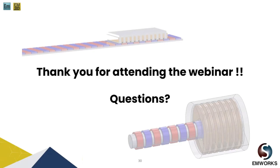of course you can have a linear induction motor, where you use a series of conductors made of copper or aluminum. You can always simulate this in the FEA tool, and as the traveling field passes through the conductor, it works mainly on the induction motor principle. It generates a current flow in the conductor, and you have a magnetic field to push the rotor in a linear fashion. So you can have a linear induction motor without permanent magnets. Also, you can design a linear reluctance motor with the same principle we use for the rotary motor.